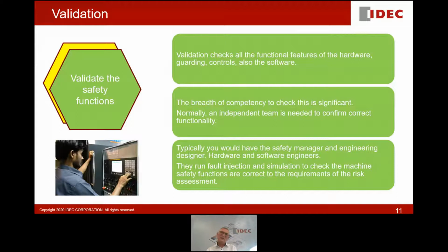And when the tests and validations are going on, there's quite complicated work that takes place. We create faults, we inject faults, we put errors in. It's a little bit like, probably a little bit severe, but when you're driving along the road and you put your foot on the brake, it works every time. That's because both brake circuits are working. Fault injection would be to cut one of the brake circuits and see whether or not you still stop.